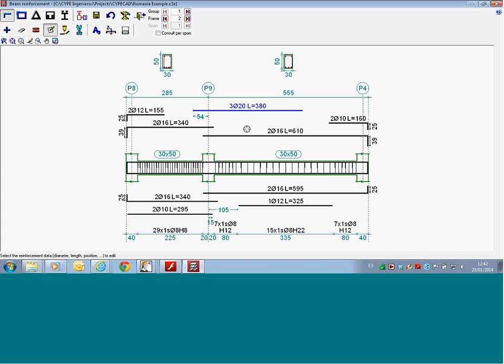And here we can say that now is when the work starts for the engineer, to achieve the best results, to show the skills as an engineer, and to get the best accuracy on the results for that structure. For example, if we can save steel on the bars here, instead of the bar of 20, we can introduce the bars of 12. Then the weight of steel will reduce.